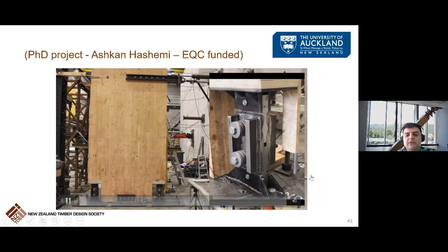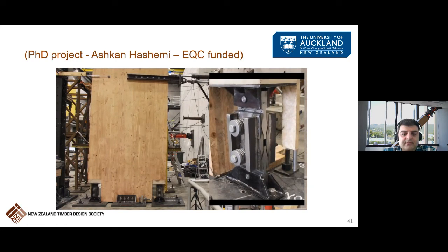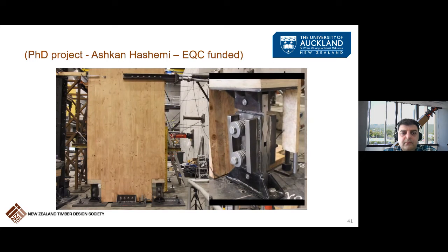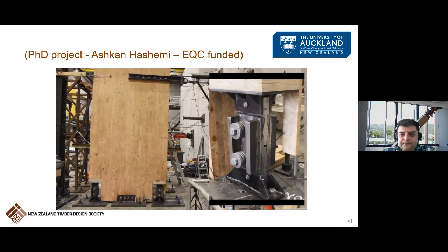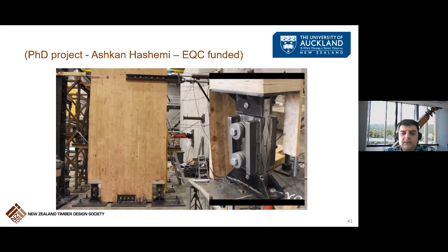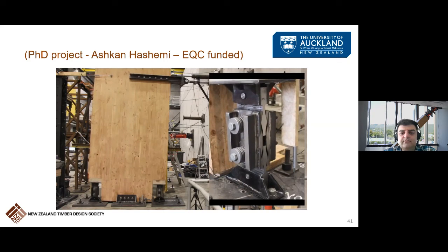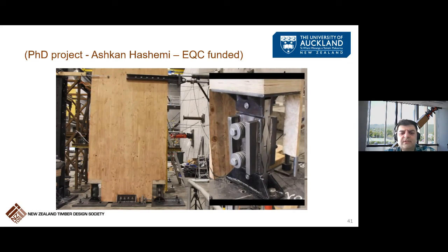A short video from the test. For this test, plus or minus 3% of drift was induced at the top of the wall. The system performed well. We didn't notice any damage in the wall, in the connections, or anywhere.